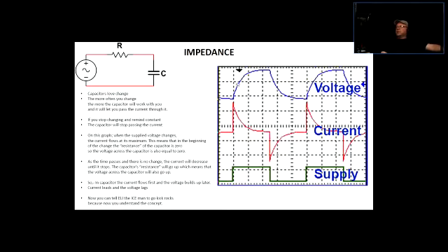Then as the voltage across the capacitor increases, the current decreases because the capacitor is charging. After some time, say 6 tau, which you probably know by now from other subjects, the capacitor is charged, the voltage reaches whatever the voltage supplied, and the current here is pretty much nil. It doesn't exist.